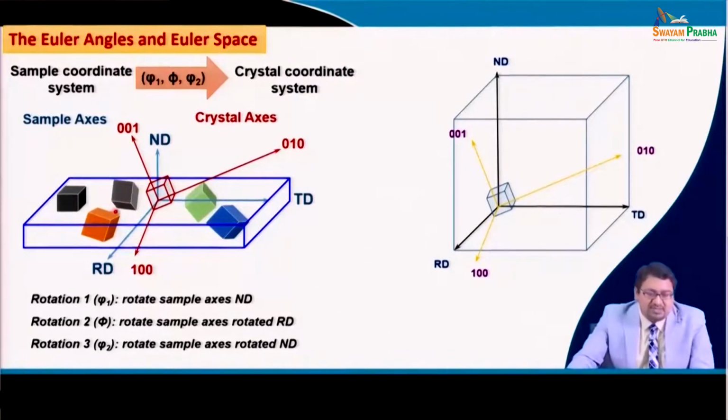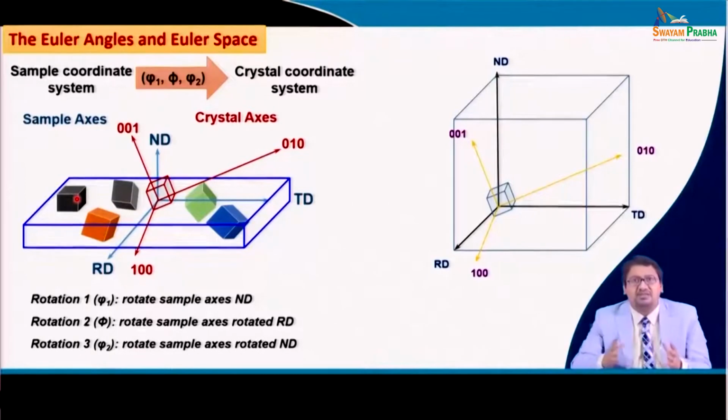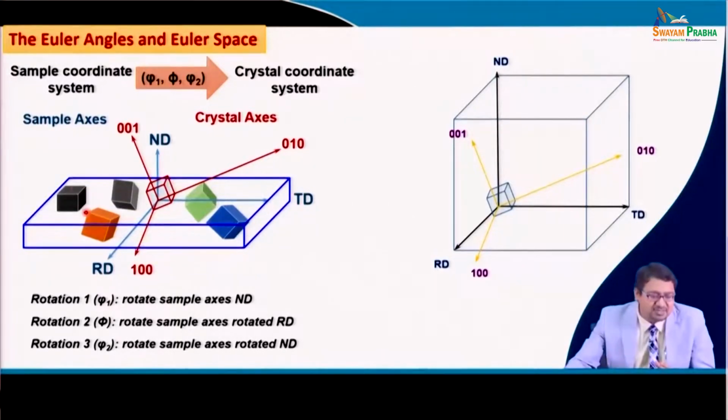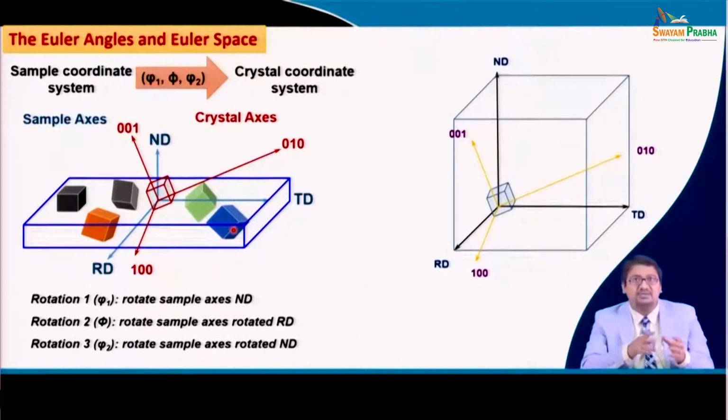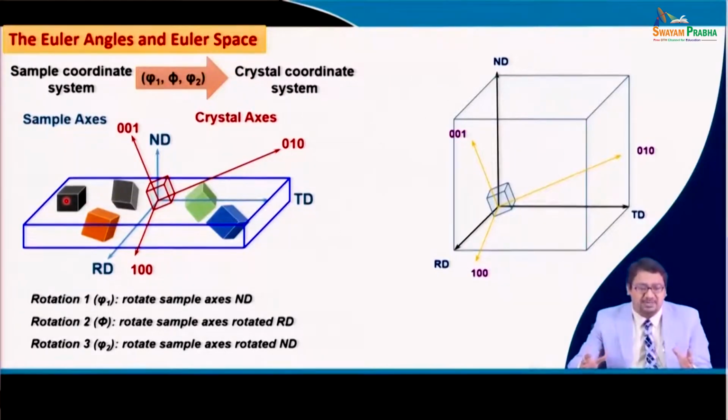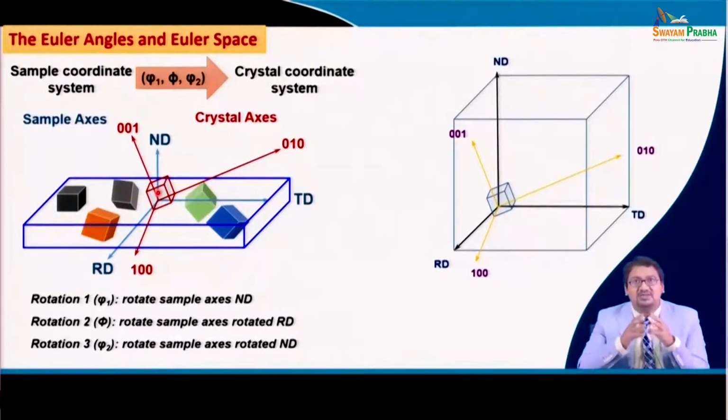So, if we take a sample like this and we have many grains or crystals in it, few crystals have this orientation, few crystals have these, and even though they have, say for example, this orientation, the grains would be spatially separated. Now, if this particular orientation is present in a large amount, then the intensity of the texture from this orientation will come highest.